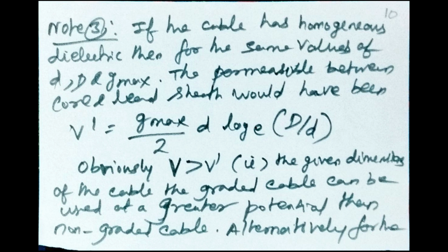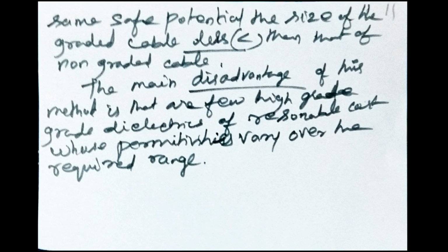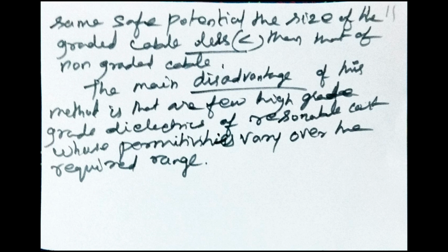Alternatively, for the same safe potential, the size of the graded cable is less than that of the non-graded cable. The main disadvantage of this method is that there are few high-grade dielectrics of reasonable cost whose permittivities vary over the required range.